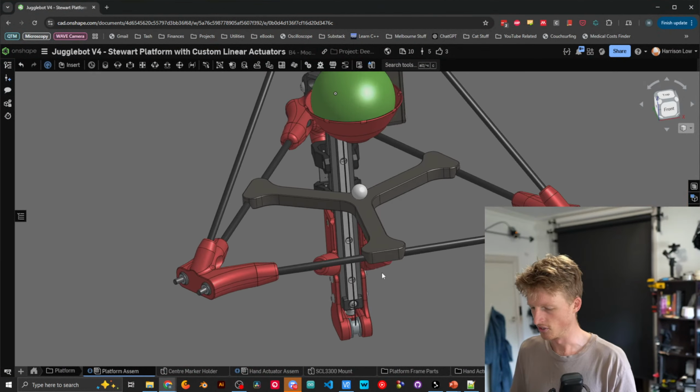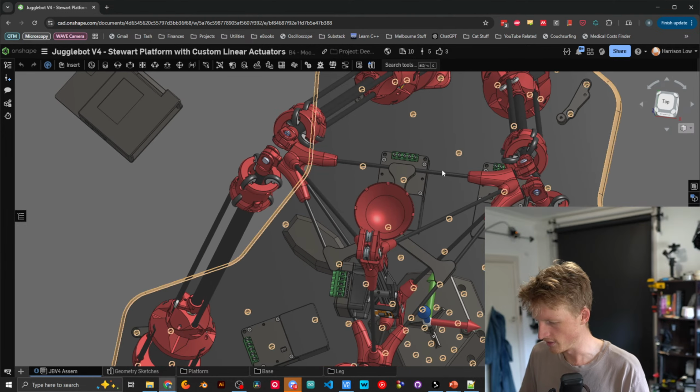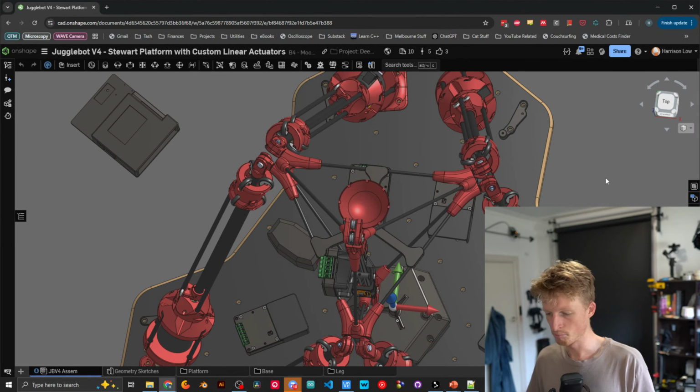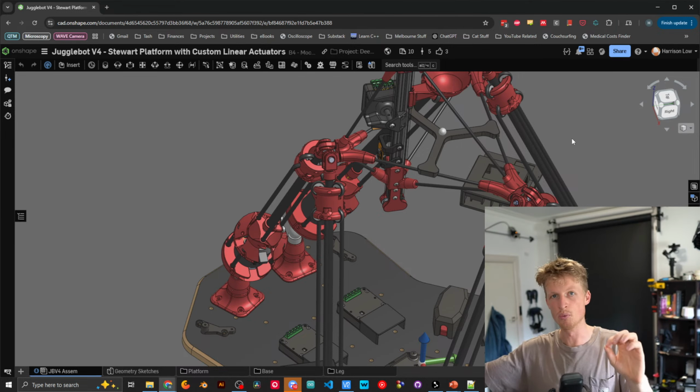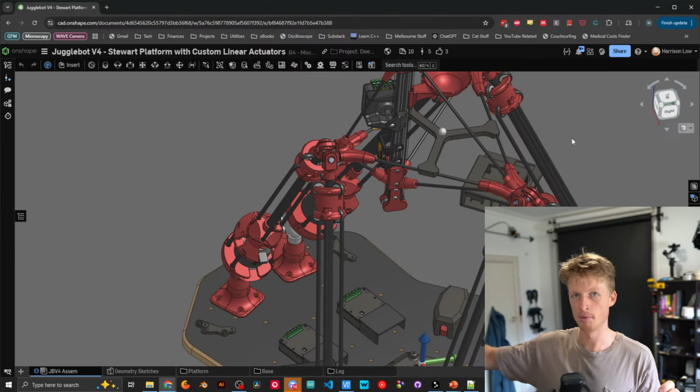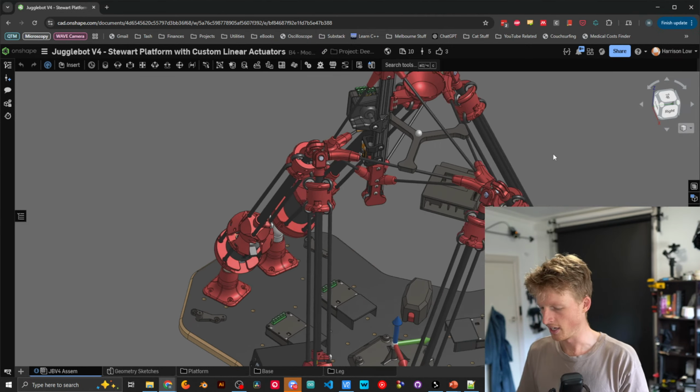Let's actually, if we go into the big assembly, we can see how these things are oriented. So we can see our main triad down there. This rod is aligned with the x-axis, so I'm hoping to use that one as the x-axis. But there is no rod in line with the y-axis, which is pointing forwards. However, when you do this realignment, when you're doing that rotation, the software asks you to find, for the y-axis at least, two points that when projected into the YZ plane make up the y-axis. So they get rid of all of the x coordinates.